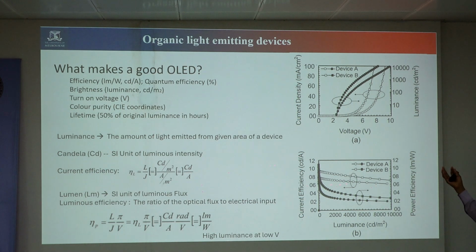In the OLED case, it is the opposite. How many photons we get out, given the electrons, because we are injecting electricity, holes and electrons, and we get light out. So how much light you get as output with respect to how much you inject, that is your efficiency here. Basically you have two: one is current efficiency, the other is luminance efficiency. There are two efficiencies for emitting.